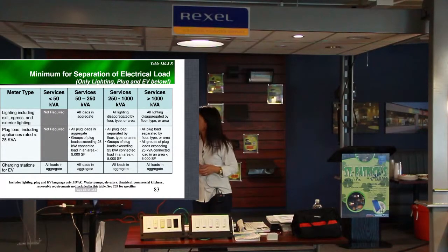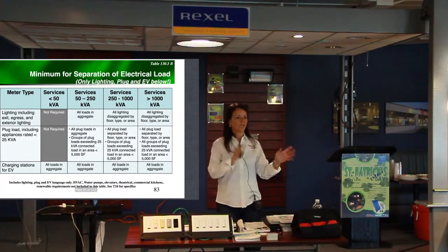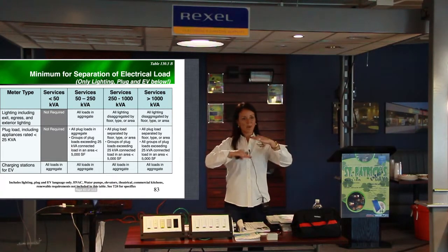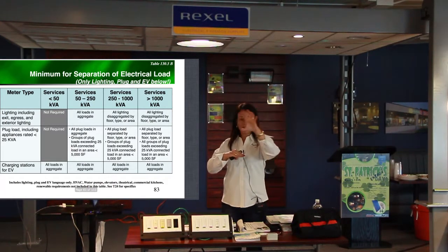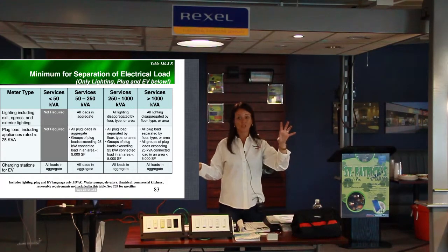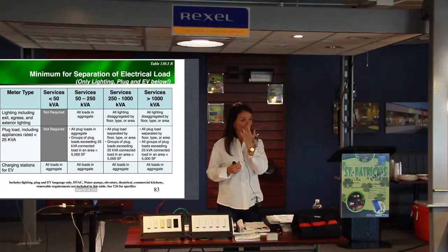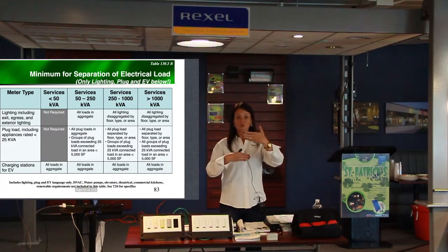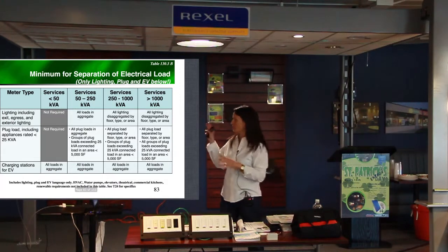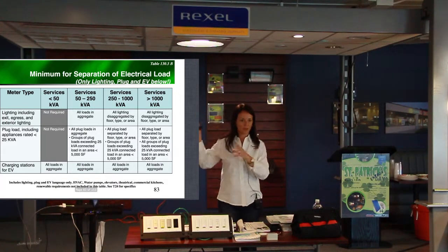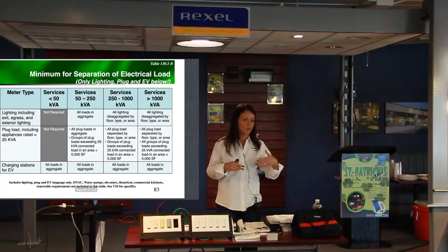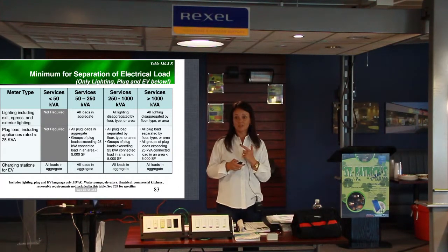about separating electrical loads: lighting and plug loads. What they're asking for is almost separating electrical power for lighting from the receptacles, the plug loads. And there's a new section on plug load controllers. So now you have to measure those two separately and be able to control those two separately. That can be a very, very lengthy topic. I'm just going to leave that chart. Feel free to read more about it, but keep an eye on it, because that's a tough one to meet.